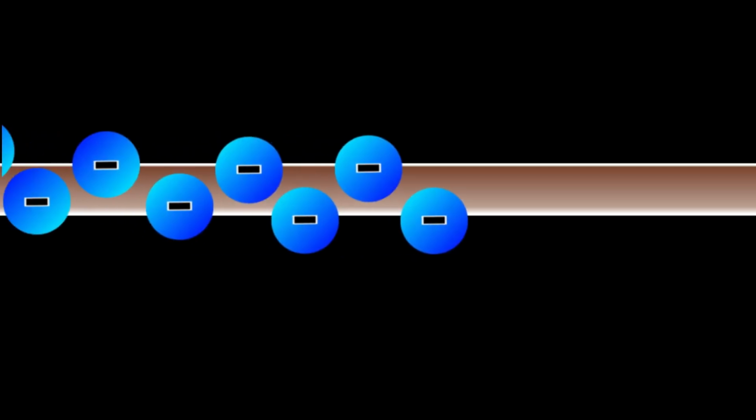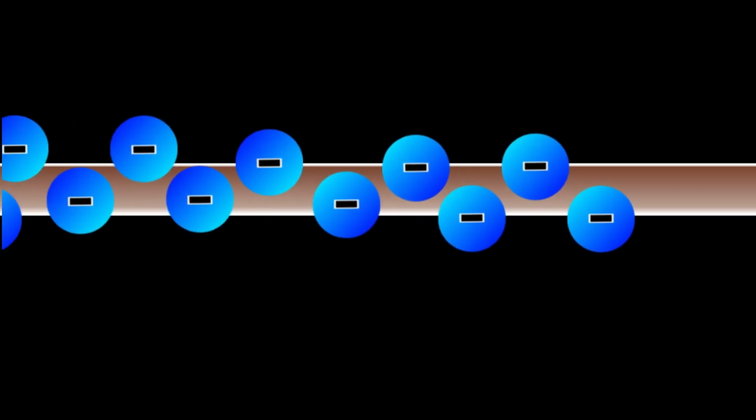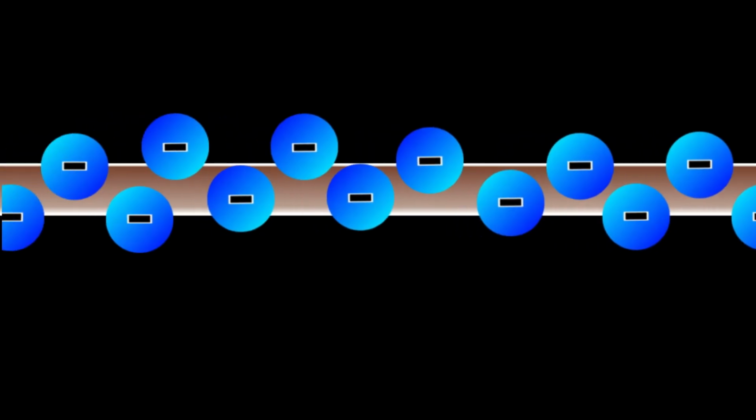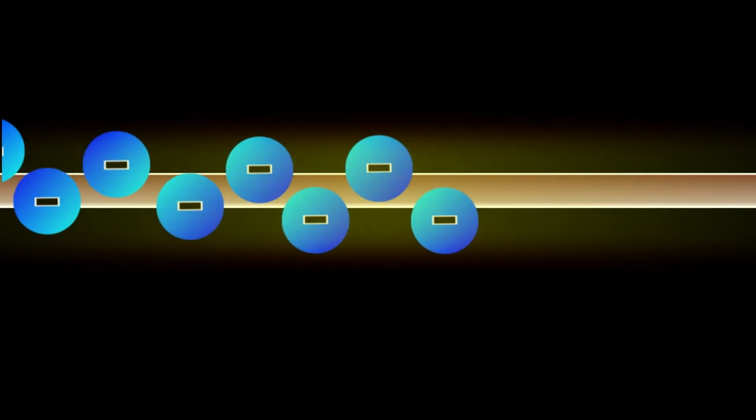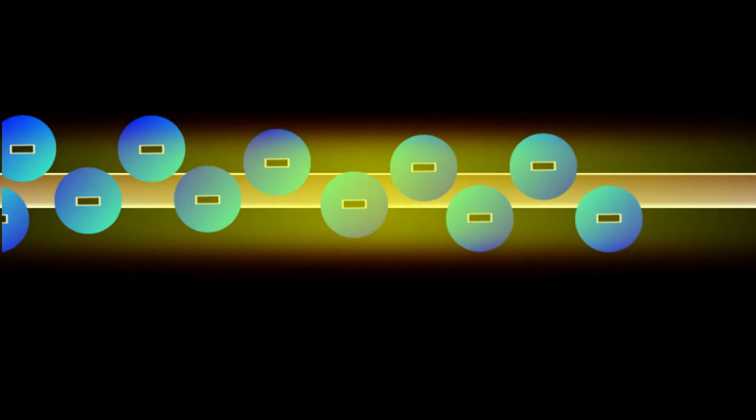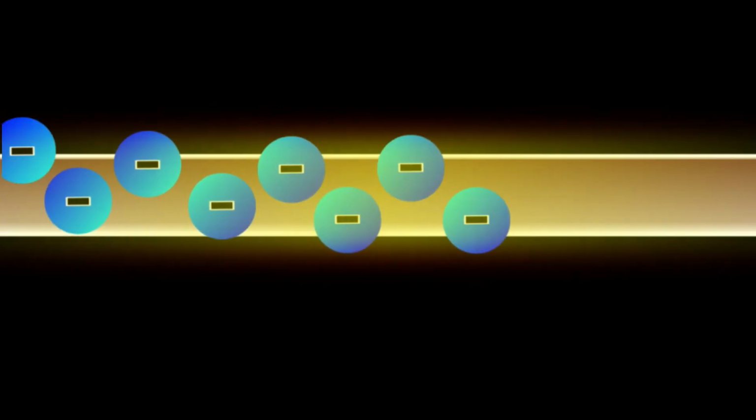You can think of electrons as tiny balls that move along the path of the circuit, through the conductors. Many metals are conductors. Some conductors are better than others. A metal like copper is pretty good at conducting electrons. Some materials and alloys, like nichrome, will convert electricity to heat and do not work well for transporting electricity. Copper wire will also heat up if too much electricity is passed through it, and this heating can be reduced by increasing the diameter of the wire.